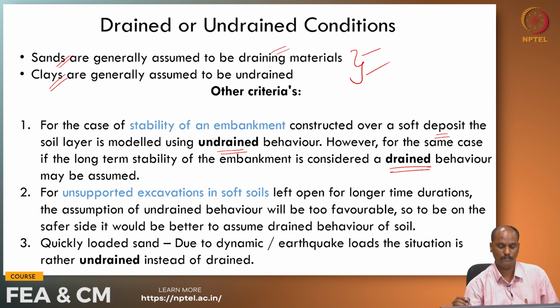Okay. So, it is again left to the discretion of the designer or the person analyzing it. We have to think about the real scenario and the fundamentals on which these finite element models work, for which a strong knowledge in geotechnical engineering is required. Especially in the case of unsupported excavations in soft soils left open for longer durations, undrained behavior will be too favorable. So, to be on the safer side, it would be better to assume a drained behavior also.